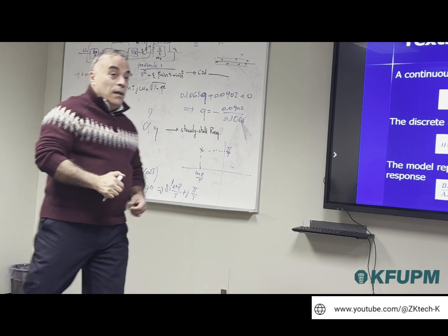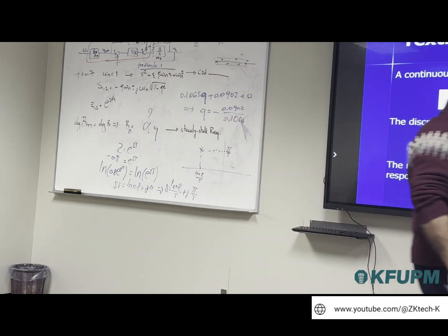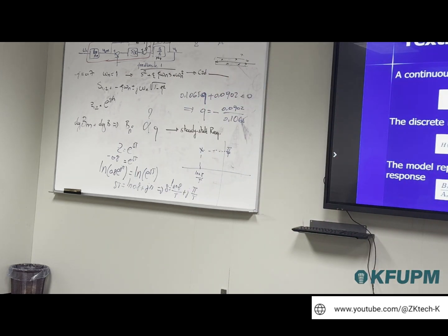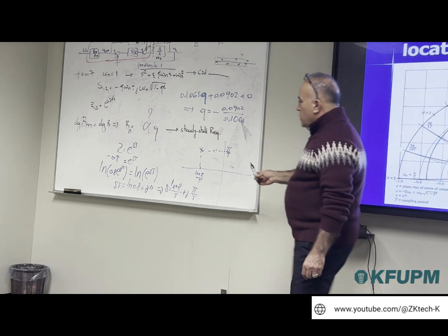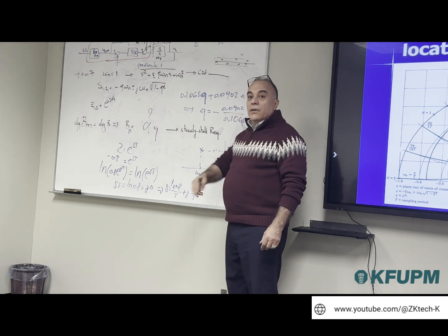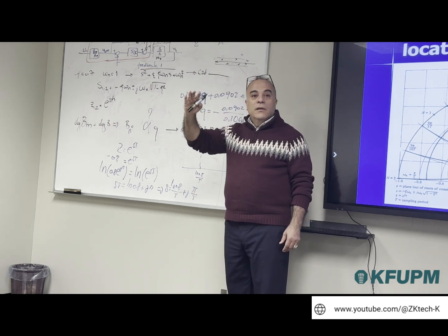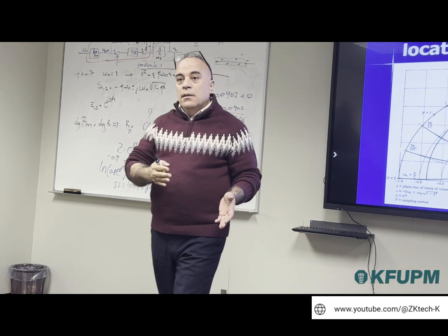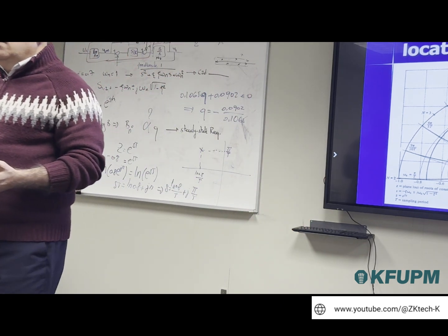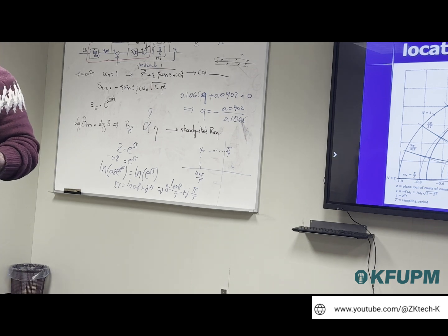Right? And now we said B minus will have to contain all the bad zeros. And the bad zeros are either underdamped zeros or zeros that are completely unstable. For this system, it contains a zero, which is stable zero, but the zero will create oscillation. And here is your judgment. You can decide that this is acceptable. You can decide that this is not acceptable.